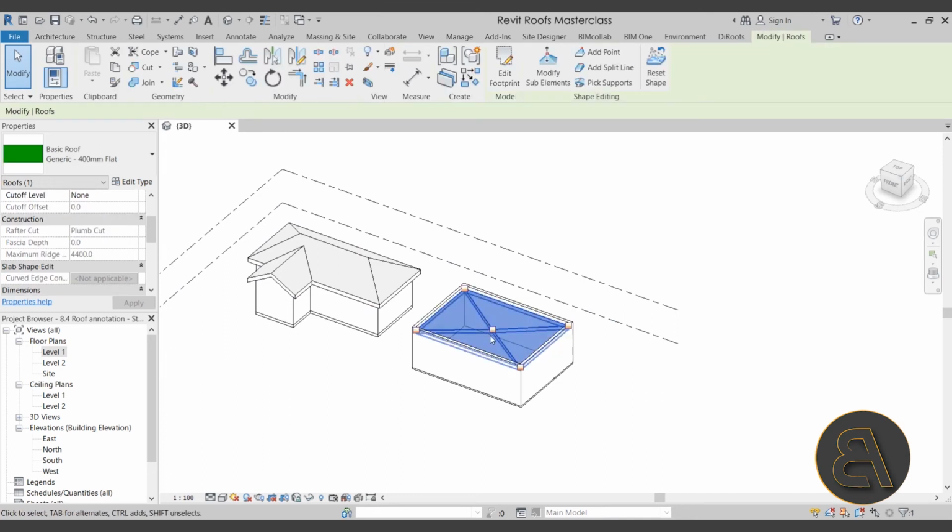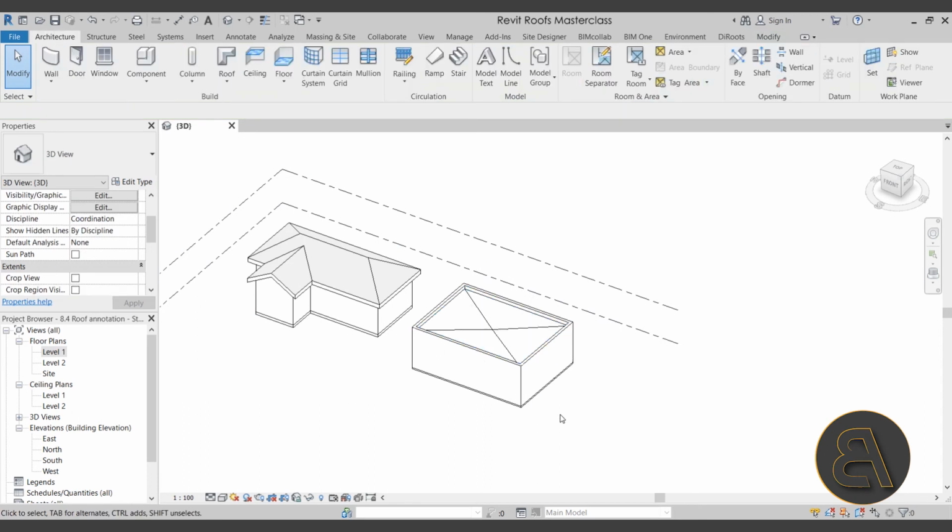from this roof when I selected with the shape editing tools, we have modified it a little bit just to include just a little bit of slope, because as I have mentioned numerous times in this course, you do have to have some sort of slope even on a flat roof, and it makes sense to document that when it comes to annotation and annotating. So that's why I included that for this video.